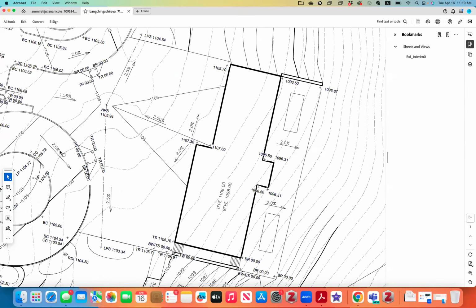There's different ways of doing it. You could put one more little thing here and say scupper for collecting roof water. Or you could put a trench drain over here and say trench drain for roof water. It's basically by labeling. You don't have to design those details out, but you label it so that we know those are for the roof water. Okay. Yeah, it's a simplified way.